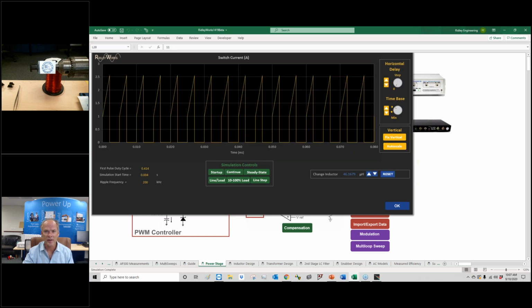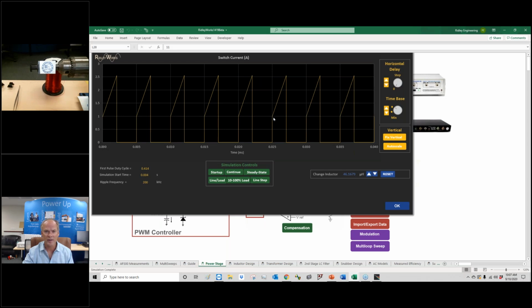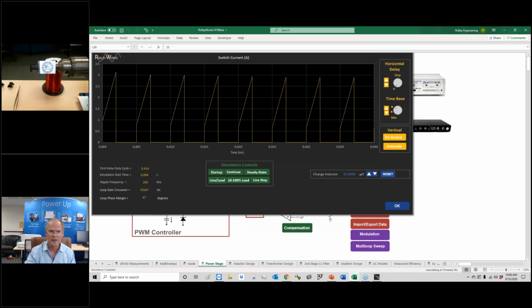And you can see our primary inductor waveform. So there's a step of about 1 amp at the beginning, and then there's a ramp of about 1.5 amps. Now this is all about the size inductor that we choose for our converter. And we're running in continuous conduction mode here, but it's not fixed that you have to do that. Around 24 watts, some people would design continuous mode, some people would design discontinuous. If you want to see discontinuous, we just make the inductor smaller.